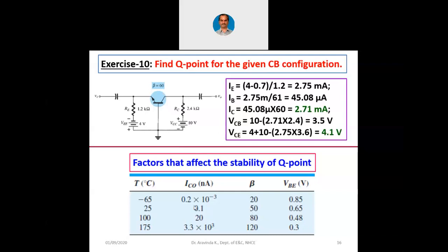But at different temperatures, the same transistor will have different beta. So recall the point which I was telling earlier, that even if we have the best bias circuitry, its Q point gets affected to some extent. So we have to have a circuit which should not depend on beta itself. That was the point I was telling you from the beginning, that we want a biasing circuitry where the Q point should remain stable, which means we should not consider beta at all.